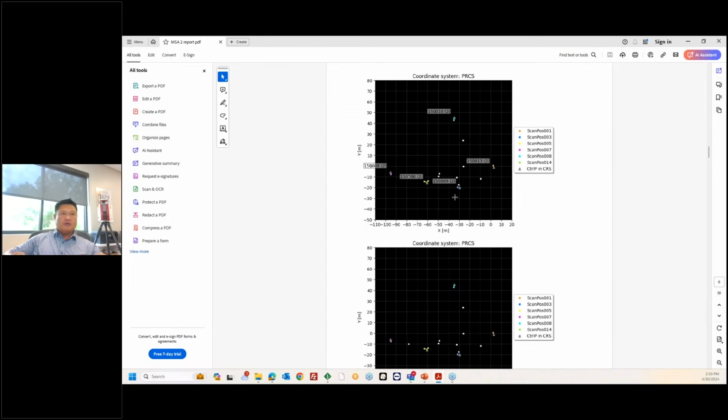Just think of it as you're building. I have to give credit to my colleague that gave me this analogy. You're building a puzzle on a table. When you're done with that complex puzzle, you pick it up and then you resection it down to your survey control, right? Our software allows us to put a weight to force, whether you want to emphasize the survey control registration, or if your control hasn't been leveled and it's just floating, like RTK, for example, you want to put a higher weight on the planes. Otherwise, it might break your scan apart. So we have a different workflow for all that.